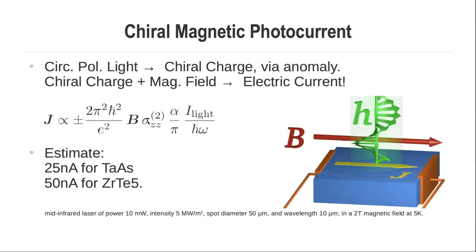Two things. First of all, when I say total current, I am referring to the total current that is generated, it does not depend on the conductivity. I will come to that in a second. But the current you take out with a probe will depend on the resistance of the sample just because of the measurement technique. But I suppose that's not what you're referring to. What you're saying is that the illuminated area of the material, the skin depth, will depend on the conductivity. Yes. And so the amount of material in which you generate your current density will decrease with increasing conductivity.